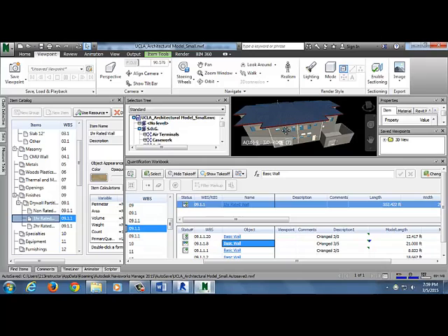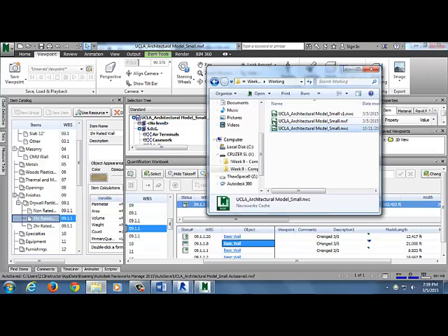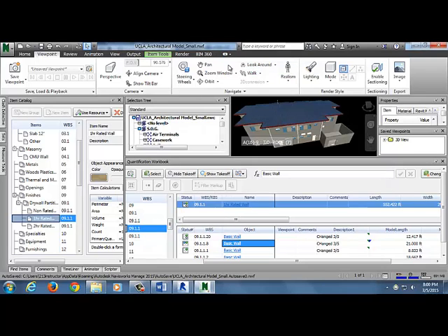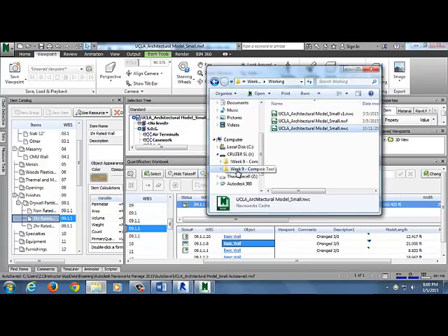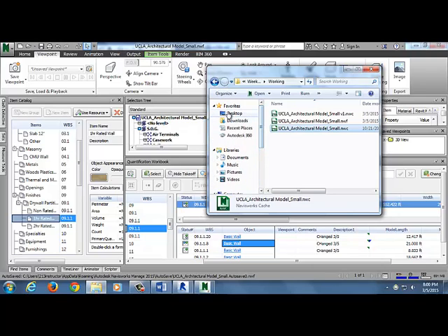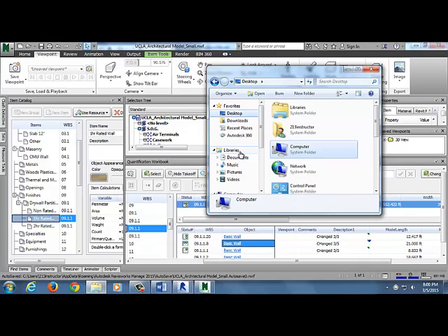In Excel, yeah. So what I would do is export the takeoff from version 1, export the takeoff from version 2, and then compare them with the IF function and see what the difference is, instead of going through every single one. So you're saying you would just do a complete takeoff on the original, and do a brand new complete takeoff, right? Yeah, totally.